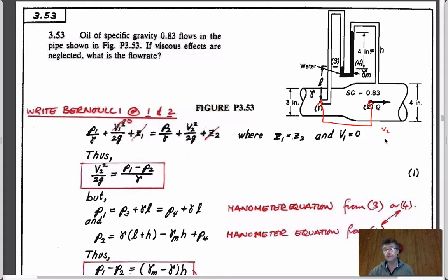If you look at the velocities, the elevations, and the pressures, then we know that V2 is not equal to 0. This would be the true velocity. And of course, velocity 2 times A2 would equal the flow rate, which I think is really what you're after in this case, I'm guessing. What's the flow rate? Q. And so we need to figure out what V2 is, and we don't know what it is. We just know it's not 0. We know an elevation. And I presume we know a pressure. We know a pressure because we can migrate this point here up through the manometer tube to be able to at least get a differential pressure between P1 and P2.